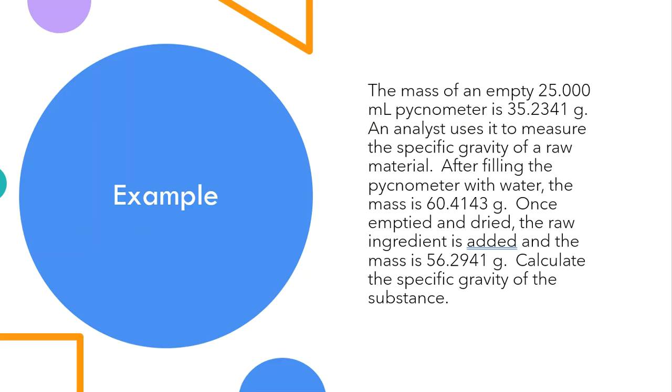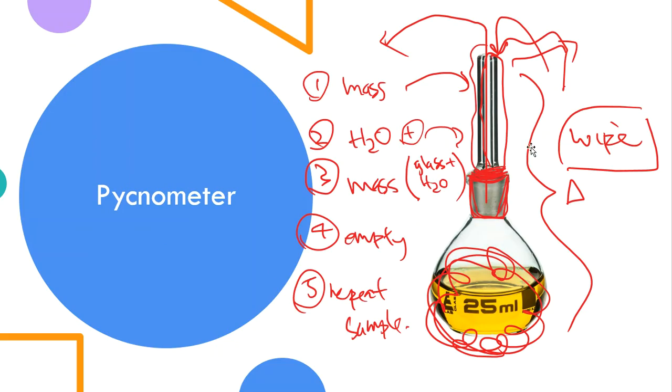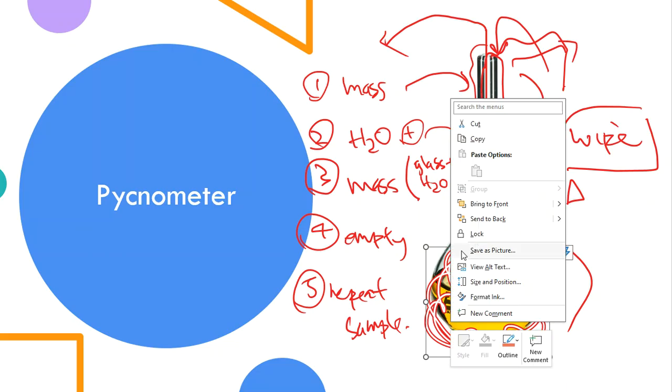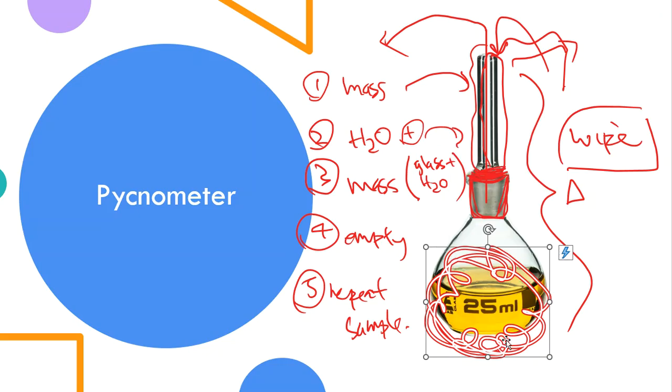Okay, so basically what's happening here is that we are once again doing method 1 that can be found in the USP. And this was method 1, all of the scribbles. Oh, but this was a pycnometer method. So we have taken a very clean and dry pycnometer and obtained a mass. And then after that, we filled it with water to the rim. We pushed on the top, squirted all the extra out of it, and then we took a mass and we recorded that mass.